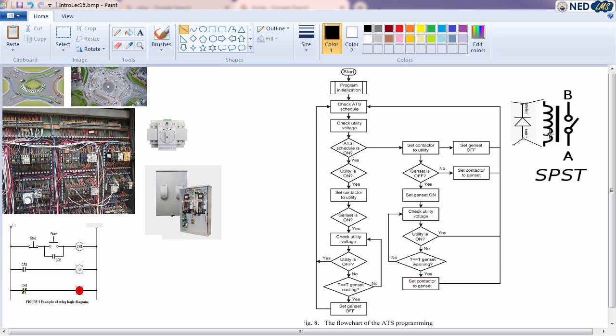The energy will dissipate in the winding of this electromechanical relay, and hopefully will not go back towards your microcontroller or control circuit. If you are using AC based relays, we use something known as RLC circuit based snubber circuits. You might be reading about that topic in your microcontroller or maybe in your power electronics course.